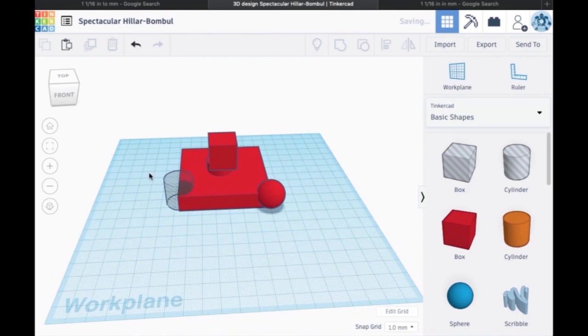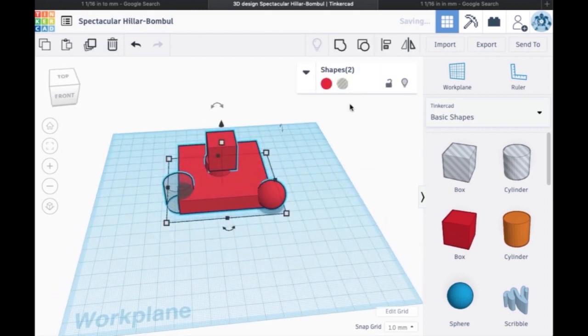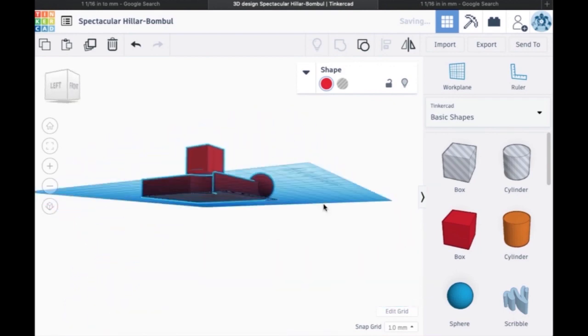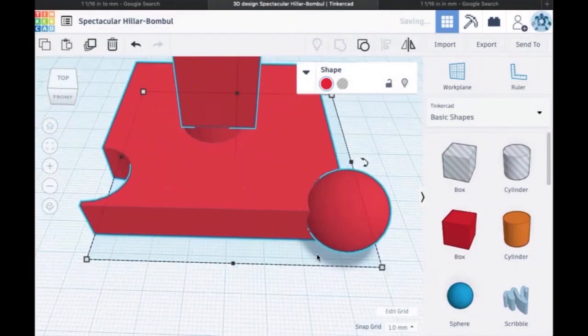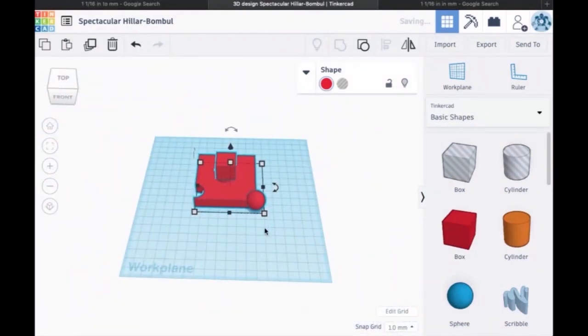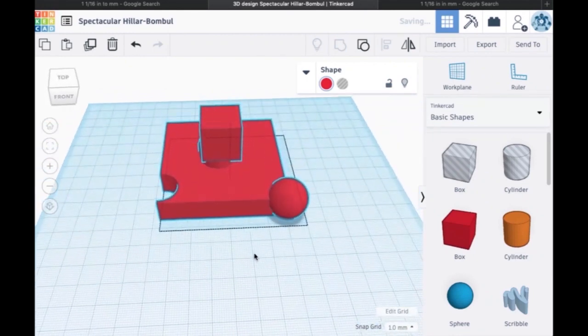As you can see, it's no longer solid, it's a wireframe. If we now do the selection, using the left click and dragging the selection box, and do the combine, instead of adding, the object takes away. It is this combination of addition and subtraction of objects that allows you to make almost anything you can imagine.